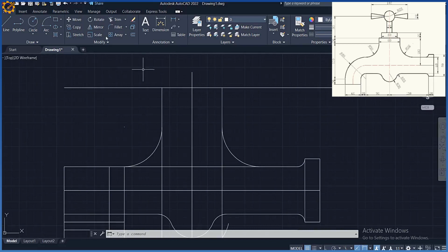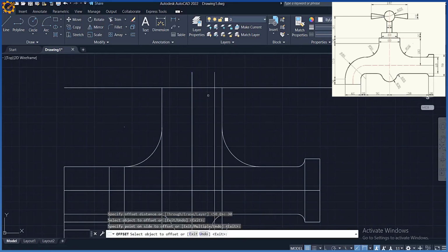So I'm picking my offset command now also, offset command, mark of 60, so that will be 30. At mark 30, enter, picking my line towards the left and towards the right there. So and the height there is what, height of 20. So escape.